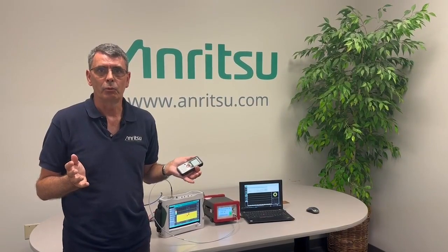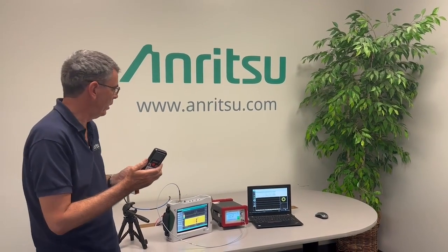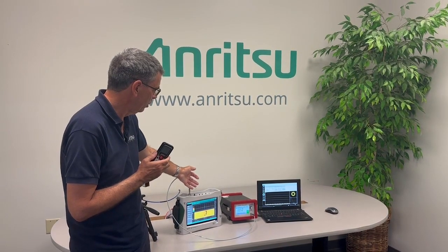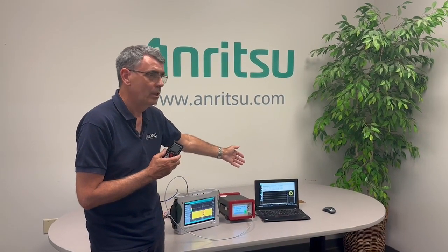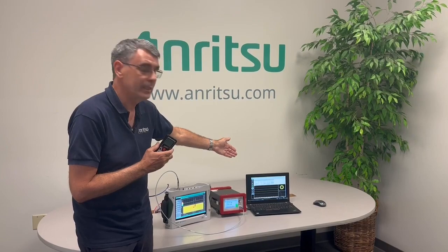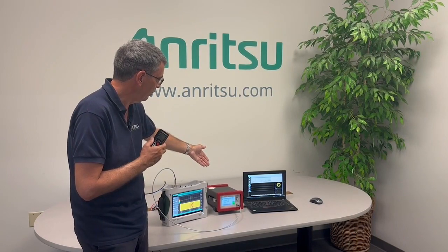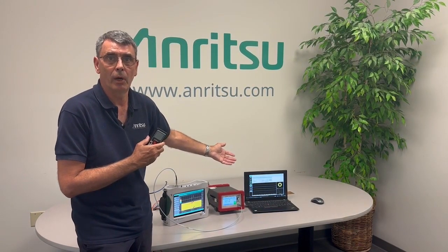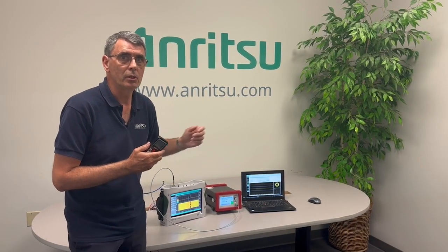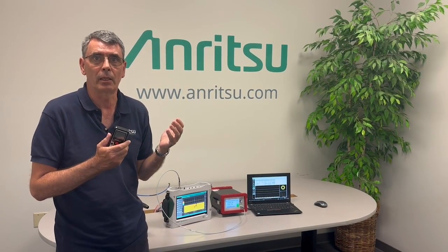What we've just done, to recap, is to transmit 24 gigahertz pulsed radar signals from this pocket radar, capture them as IQ data on the Anritsu MS-2090A Field Master Pro, pull that IQ data into the IQ Signal Master software running on the PC. We've been able to view that data on the PC itself and then convert it into a file that we can push into the AnaPico vector signal generator and play that IQ data back as a file at any frequency we want to, up to 40 gigahertz. So it's a really powerful combination of software and instrumentation there to capture and play back IQ data.